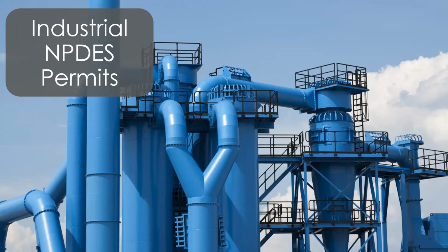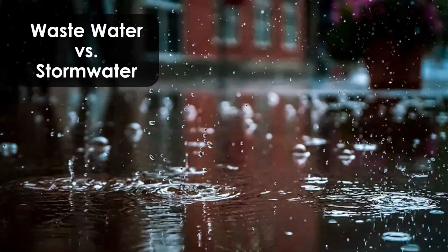All right, so after we get through all that, we're going to discuss the industrial NPDES permits, and then we'll go into construction after that. The industrial thing, the main thing to know is we're looking at only the stormwater today. There's also wastewater permitting. And to give you the difference, stormwater obviously is just rainfall, flowing off site, collecting any contaminants you have on site.